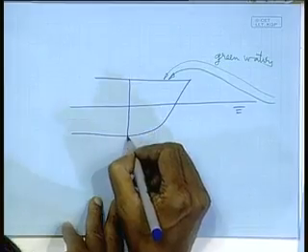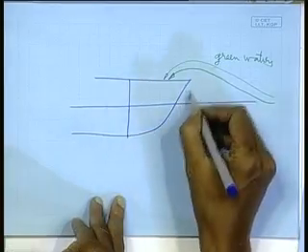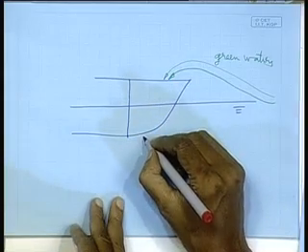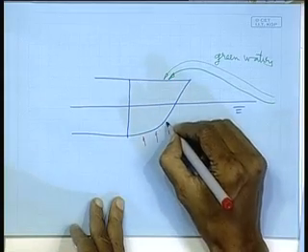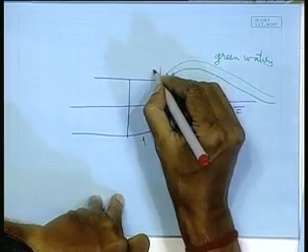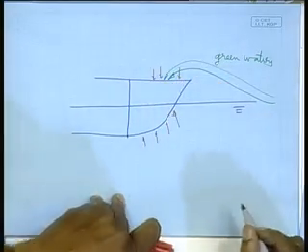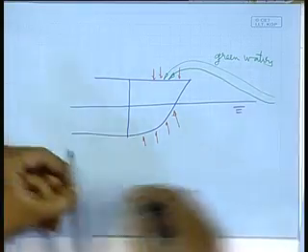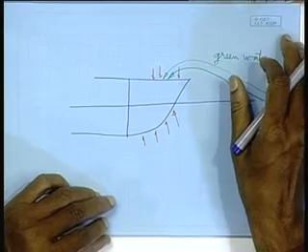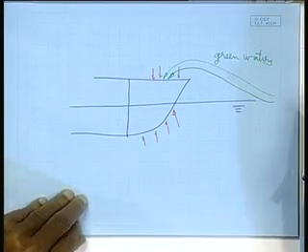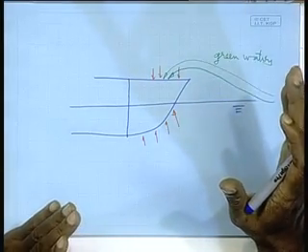So, that is how we see that the forward end has to be additionally stiffened, not only the bottom shell part of it, because the bottom shell is subjected to loading due to the slamming action or heaving action of the vessel, and this is because of the shipping in of green waters, right. It needs extra loading, though the stresses due to bending moment are near 0. So, that is how we see it is primarily the local load.